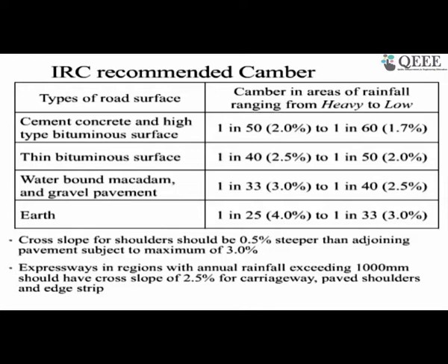And so, whenever you are constructing an expressway, which is of higher speed, that is why we are limiting the expressway camber to be 2.5% of the carriageway, and also the same thing we are providing on the paved shoulder and the strip. Why are we providing the same on the expressway? That is because if you look into the expressway, vehicles are expected to travel at a very high speed, and shoulders are going to be used when there is an emergency stop.